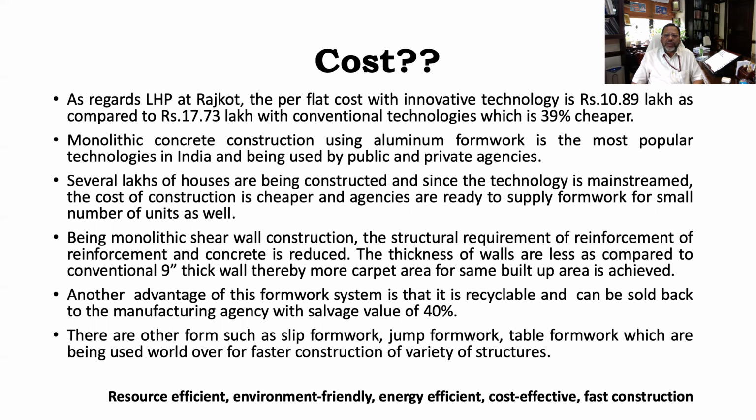In fact, using tunnel formwork, within 2 to 3 days you can construct a floor. Similarly, with aluminum formwork, also within 2 to 3 days you can construct a dwelling unit. Also, at the same time, because the construction takes place in a sequential manner, you first put the formwork, then you lay the reinforcement cage, then you do the concreting in a single pour.